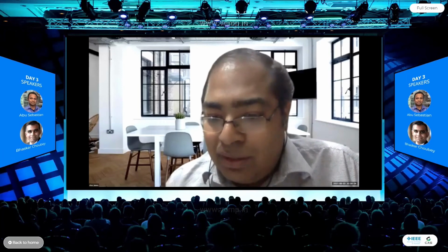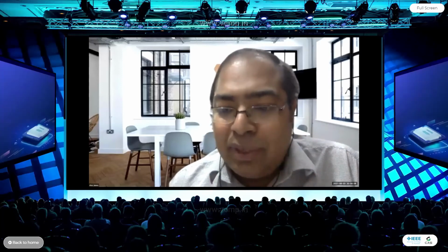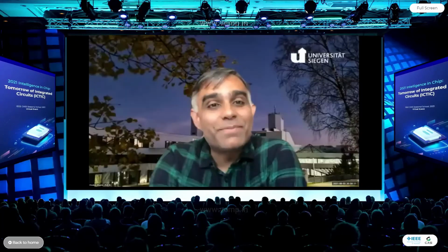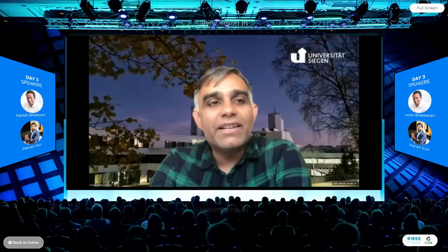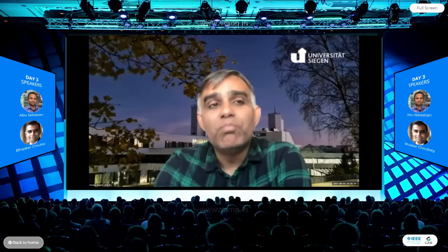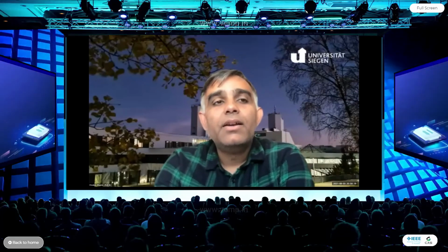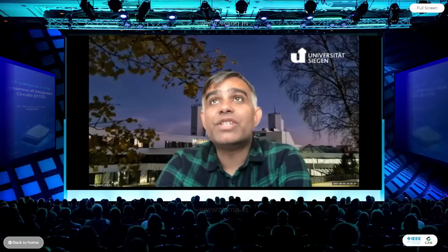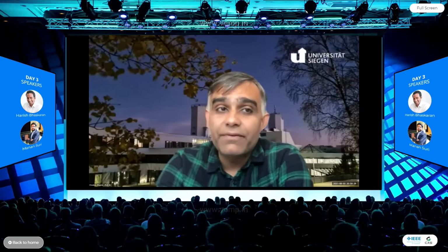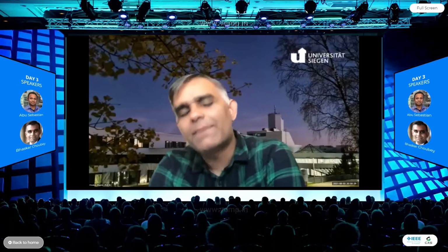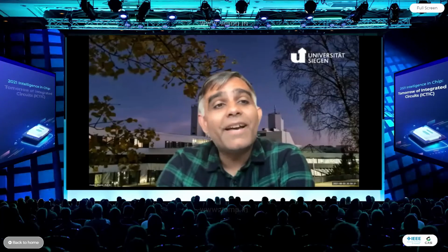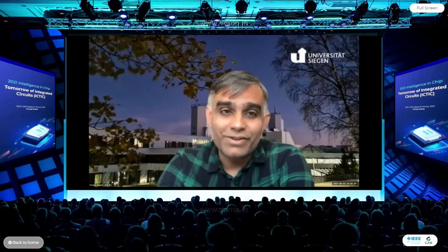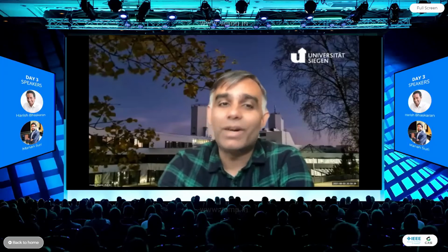Another question is, if the surrounding is moving fast, can the image sensor capture with good quality? Depends upon how fast it is moving. 30 frames per second is the standard video frame rate, which most sensors can do. People do design for very high speed moving scenes. There are cameras which can do 1,000 or 50,000 frames per second. A number of these cameras have been designed for defense applications, so they are generally export controlled from one country to another.